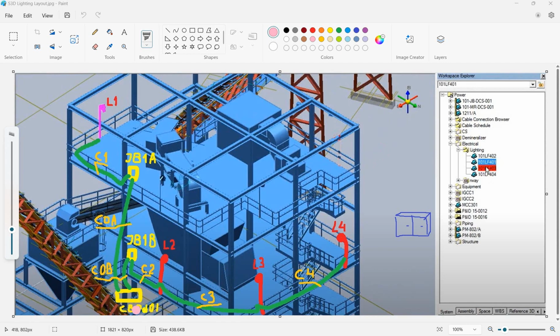In this example, I created a circuit breaker panel distributing power to field junction boxes, which in turn are wired to lighting fixtures in a daisy chain. I also defined some loading parameters of the lighting fixtures sourced from the selected equipment catalogs.